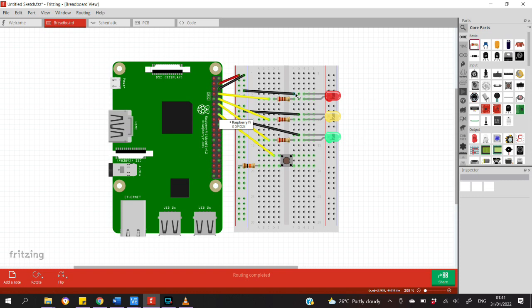And of course, the cathode is connected to the ground for each LED. And we power this rail with 5 volts, and that is connected to the grid, where one side is at 5 volts and the other is on the ground.